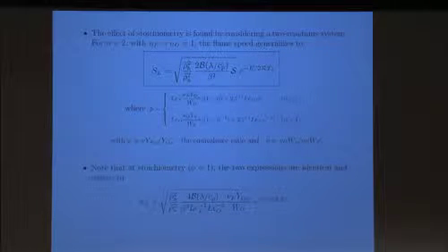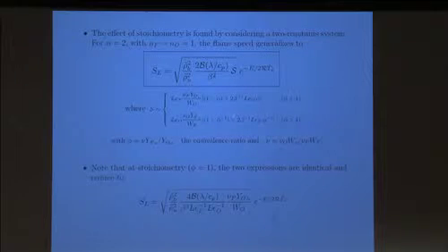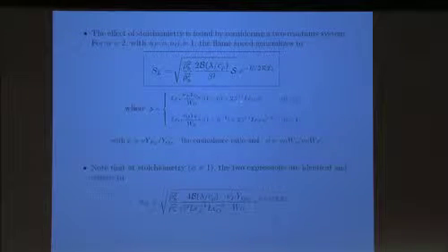Then the difference is really in this additional factor that I called S. S stands for the effect of stoichiometry, and the phi here is the equivalence ratio. So for a lean mixture, this is the change that you would anticipate. For a rich mixture, it is this, and in particular, at stoichiometry, when phi is equal to 1, since this term becomes small, being multiplied by beta minus 1, the two expressions collapse into this.